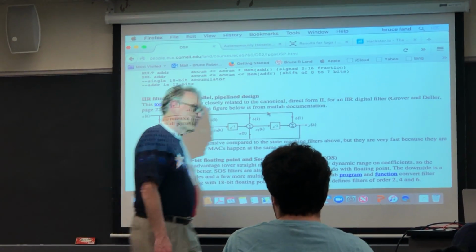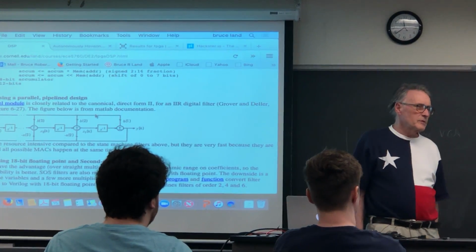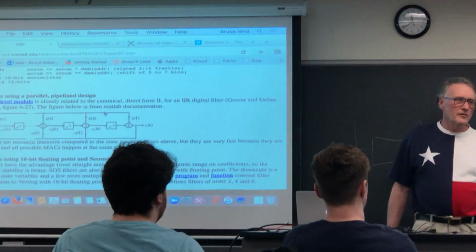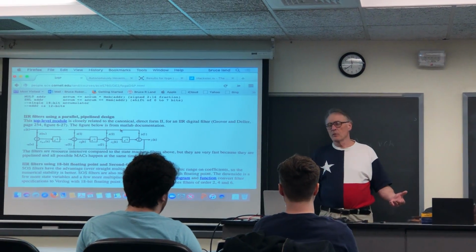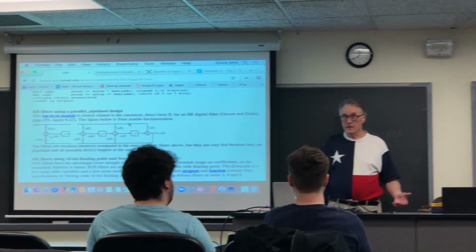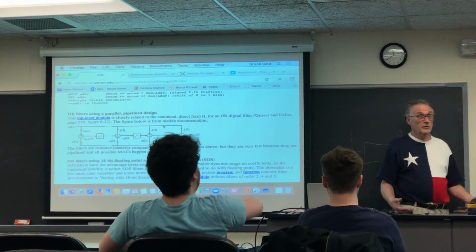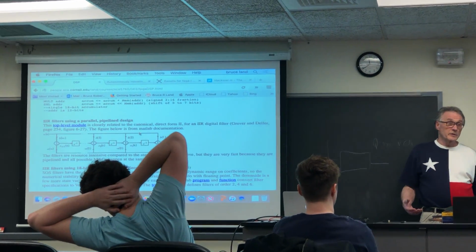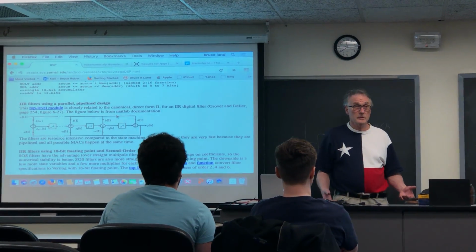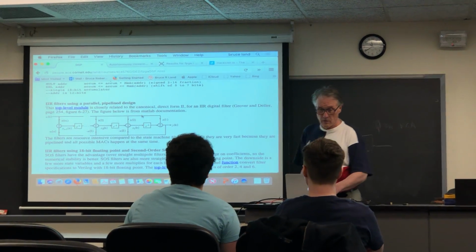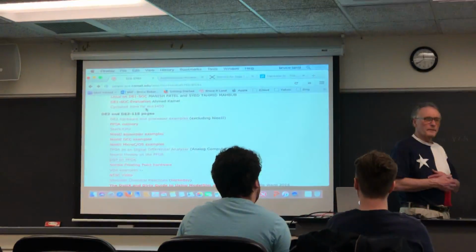And so, the audio filters that I've been building over the years have all been sequential state machines that take 8 or 10 or 15 steps to do up to, say, 6 poles of filtering. Now, because they don't take much resource, you can build a lot of these things running in parallel. I figure you could do a few thousand poles of filtering on this architecture before you run out of multipliers. Then the question is, what in the hell do you do with all that filtering capability?